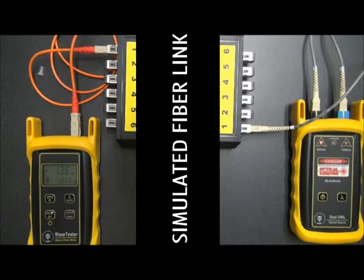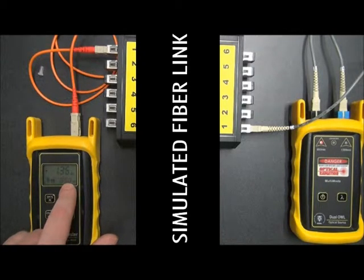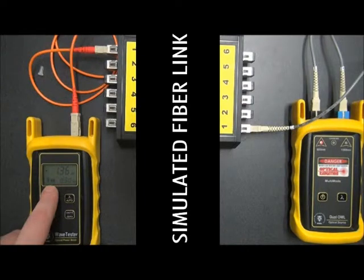So now that we have a reading here, what we want to do is store the reading by pressing the save button. Now, as you can see, it says save and then a number. Down here it said 001. That means that's test result number 1. And now that there is stored data in the meter, we have a floppy disk icon. So what we need to do now is store the readings for the rest of the fibers.